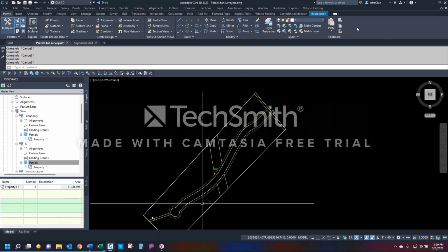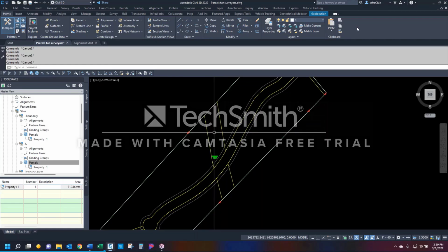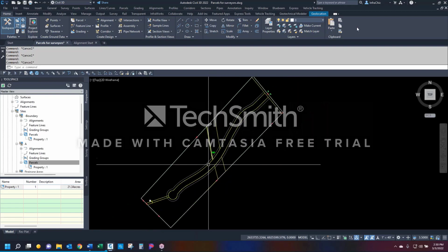The last two things to note are these 2 pipelines that run right through here. Pipelines are very important in Texas. These are oil pipelines, not natural gas. This is oil, as in coming from the oil field going to the refinery before it becomes gasoline and diesel. So there are 2 large diameter 48-inch oil pipelines in here, and this is their easement. It's like 50 feet each side of the pipe, so it's a fairly large 150-foot wide easement.